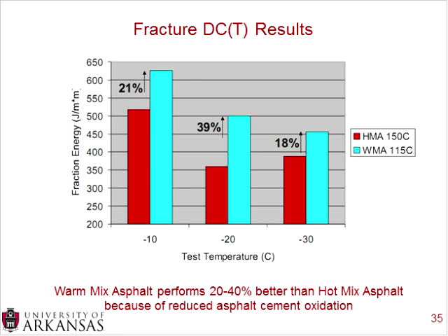And we believe this is because of the reduced asphalt cement oxidation. So as asphalt cement goes through a hot mix plant, it obviously needs to get heated up to very warm temperatures. And when it gets heated up, it actually starts oxidizing a little bit. So all of that heat, all of that oxygen in the area, it forces oxygen into the asphalt cement, which is called oxidation.